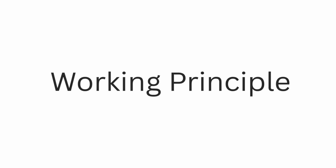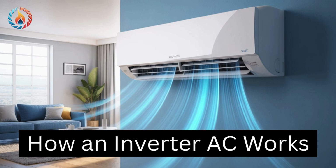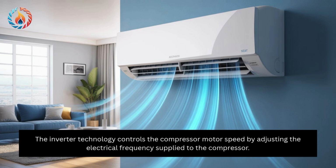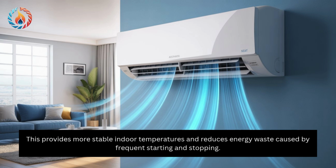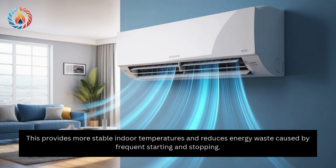Working principle: how an inverter AC works. The inverter technology controls the compressor motor speed by adjusting the electrical frequency supplied to the compressor. For example, if only 50% cooling capacity is needed, the compressor slows down and operates at a lower speed rather than stopping completely. This provides more stable indoor temperatures and reduces energy waste caused by frequent starting and stopping.